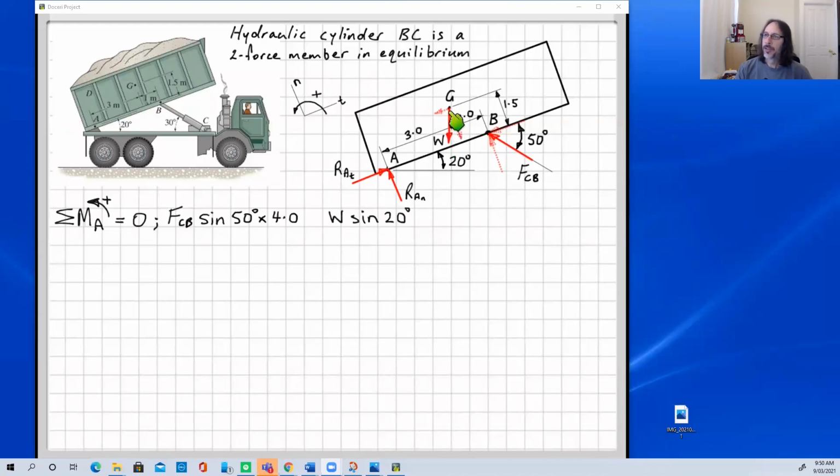We have to find the components again, because this force is not in the normal direction; it's at an angle to the normal and tangential components. Hopefully you can see that the angle in here will be 20 degrees. That's just another reason for drawing your free body diagrams large, neat and clear, because your angles look right and it helps you to do your trigonometry and geometry correctly.